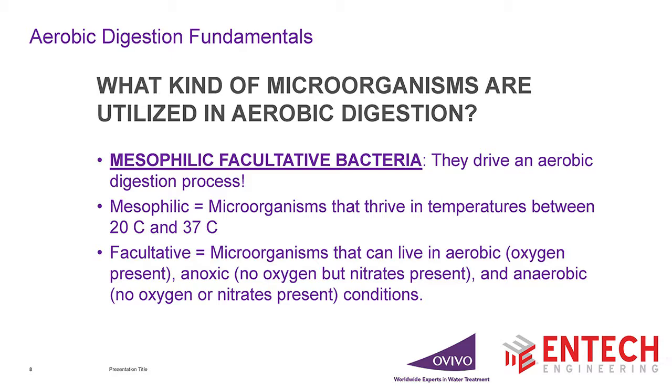As you get beyond that, they're kind of like us. 35 degrees centigrade is getting close to 100 degrees Fahrenheit, and things get kind of miserable for us when the temperature gets that high. In fact, as you get beyond this, the mesophilic organisms actually begin to die. This is the upper range for them. They can go down below it, but we have the ability to keep them at about 20 degrees or above, which helps to optimize their performance.